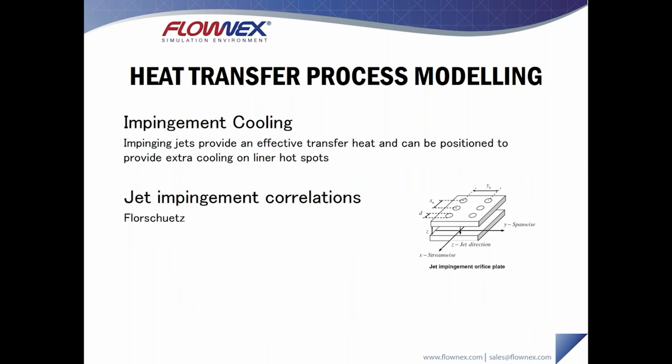Impingement cooling. So impingement jets typically provide an effective mechanism for heat transfer as well, and can be positioned to provide extra cooling on liner hotspots. There's one or two correlations for that implemented within Flownex. Again, those are pretty standard correlations for the gas turbine industry.